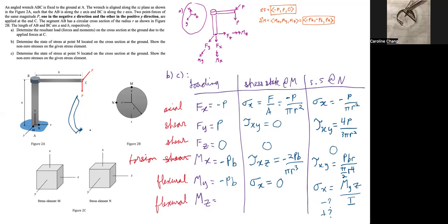So the stress element at n will be under compression, so we have to add a negative sign here. So it'll be a negative stress state. If it were over here, it'll be under tension, since we can see that we are stretching the atoms by curving it, and we are compressing the atoms over here, because it's being kind of squeezed together.